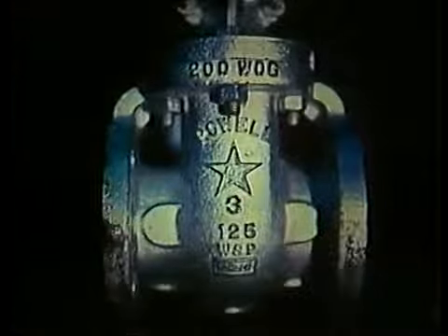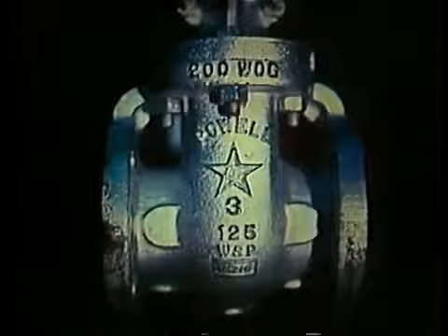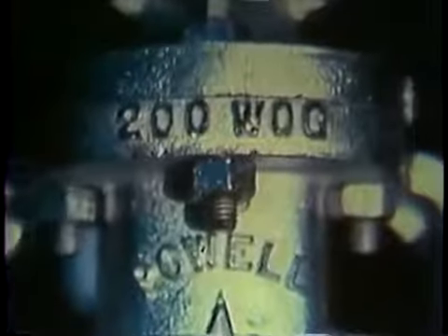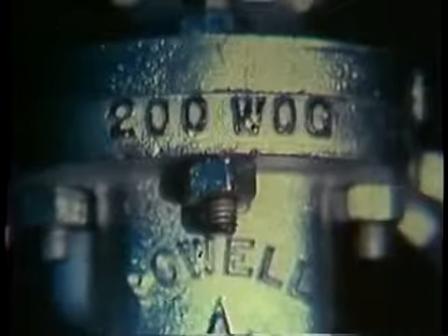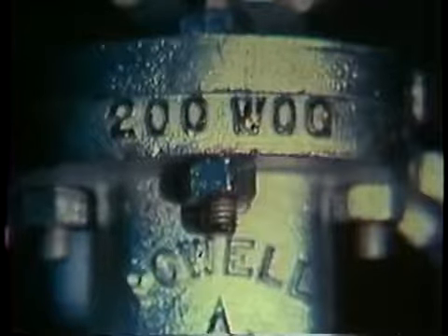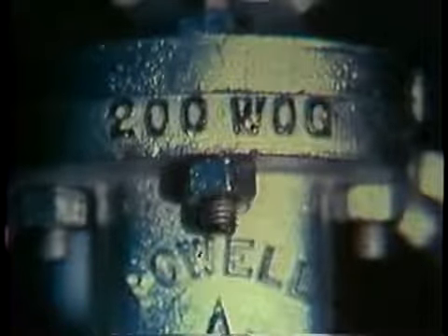You'll find service markings on the valve too. These will indicate the operating range of the valve. For example, on this valve, the number 200 is the maximum allowable pressure that can safely be placed on the valve. These letters, WOG, stand for cold water, W, oil, O, and gas, G. They are for pressure ratings other than steam.